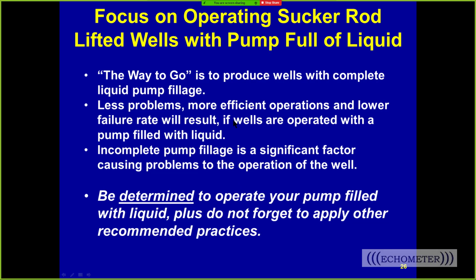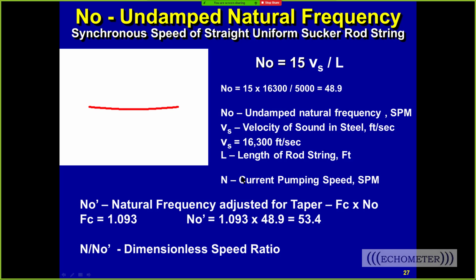So the way to go is a complete pump filled with liquid. And that's the way to go. You'll have longer life. You'll have fewer problems. If you have incomplete pump fillage, you'll significantly impact the life of your equipment. And so you should be determined to maintain a full pump.